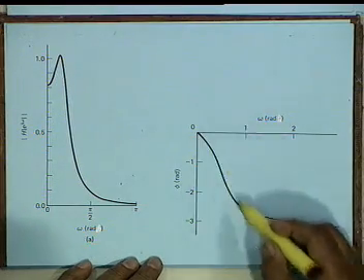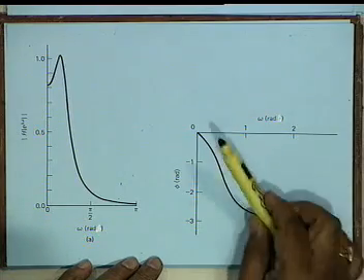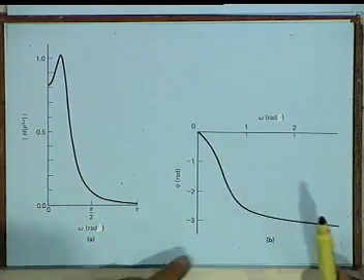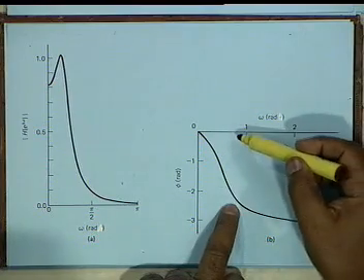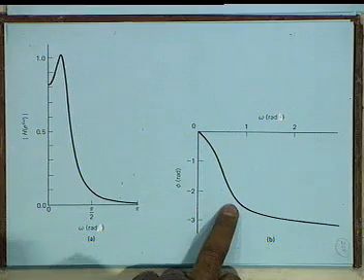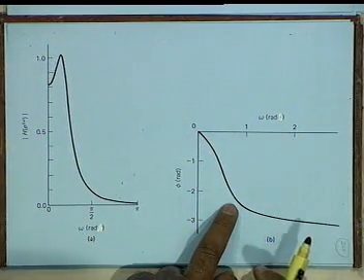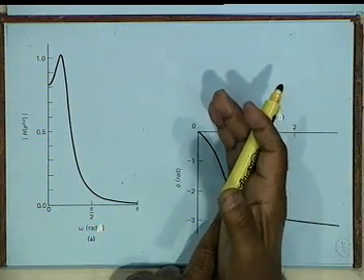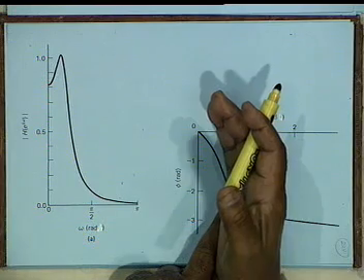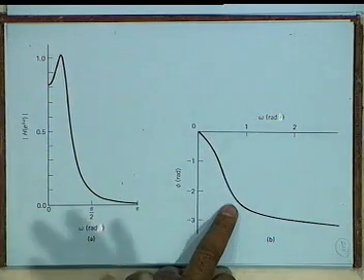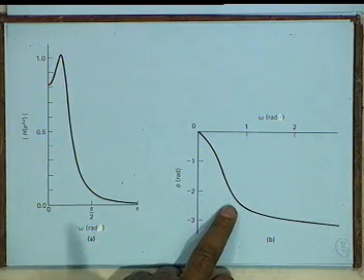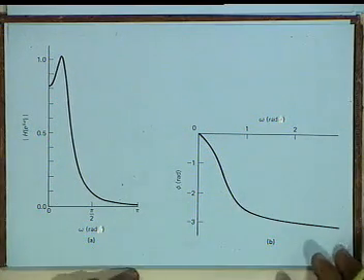As far as phase is concerned, the nonlinear phase is approximately linear up to about 0.8 radians, and then the nonlinearity starts. So if your passband is confined to this, you can reasonably be certain there will be no delay distortion. If you go beyond this, then you have to use an all pass filter.